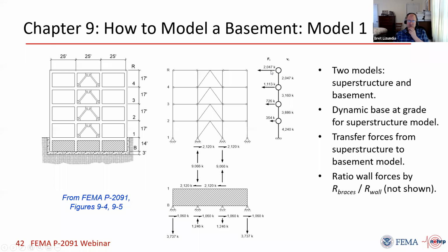So you can see, 2,000 kips at the roof is our force at the roof level. Then the shear immediately underneath that's the same 2,000. And then by the time we get to the bottom of that, there's 40 kips of shear going through this frame or this building. Then a separate model would say, okay, I'm going to take those loads that come down, both their horizontal and their overturning loads, and I'm going to apply them to a 1-story shear wall bottom that has its own characteristics and its own shear, and then just linearly combine the 2.